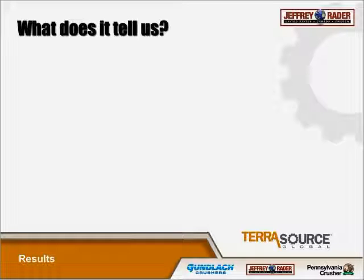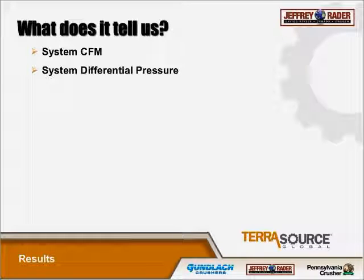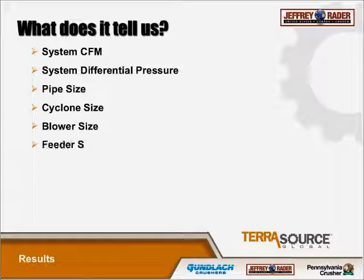So what does that tell us? System CFM is going to be important for our calculations. The differential pressure is also going to be very important. Pipe size, obviously. Size of the cyclone required, the blower size, and the feeder size. Now, all these components are selected based on that given set of criteria and are unique to that criteria. If anything changes, the system likely will not operate correctly.